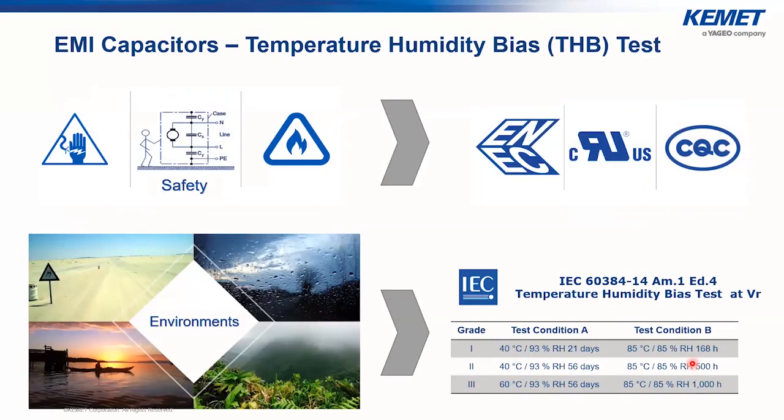So today, the main drivers for our roadmap for these EMI capacitors are really the ambient temperature, and the capacitors are more and more required to be able to operate in harsh environmental conditions. And so in addition to the AEC-Q200 requirements, we have to follow now what we call the THB test performance that is defined in the IEC 60384-14, where we have the definition of the protection against humidity.